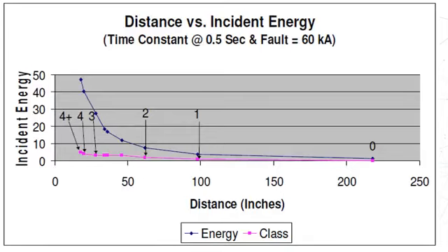For example, I was initially given a task of performing a thermography at a working distance of 36 inches. I performed the risk assessment, and the incident energy was around 8 cals per centimeter square. I was wearing a 10 to 12 cals per centimeter square suit. During the thermography, I identified that there is a loose connection. Now, can a qualified person perform that repair work? Can I tighten that connection because a hot spot was showing? It's not allowed because it comes under the scope change.